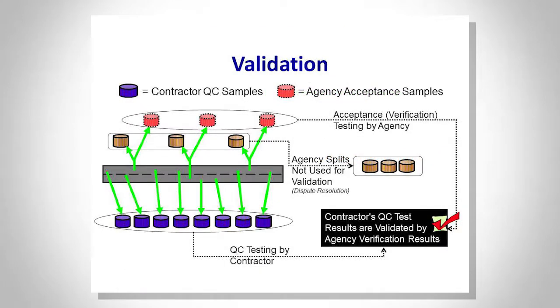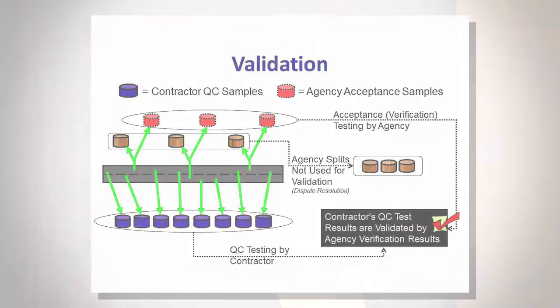Got a mat, you got the samples. Do the split samples from the state, take the test. Now you need to validate them. Still have the 3 referee samples in case there's discrepancies and an appeal is needed. Take the 2 and you want to validate them. See if they compare. So that's what our technical advisory talks about, using contractors' tests. State does their test, matching up, see if they're correlated, and see if they're within your tolerance that you may or may not want to allow.